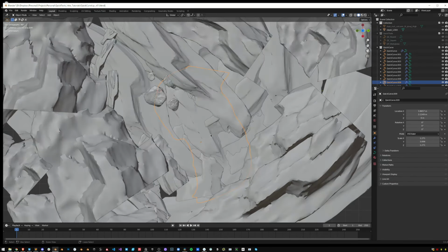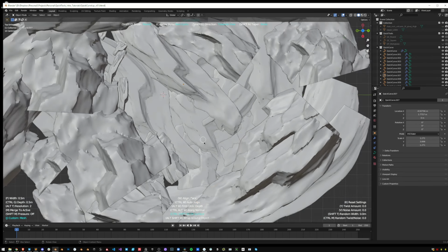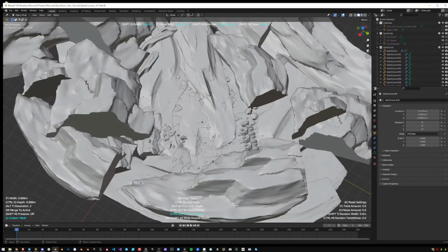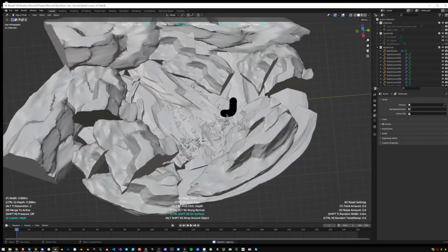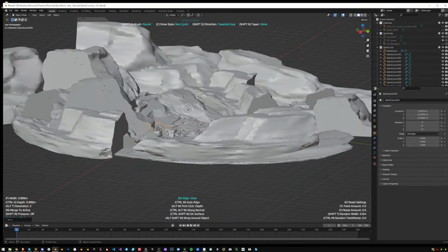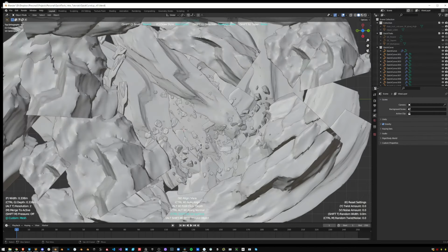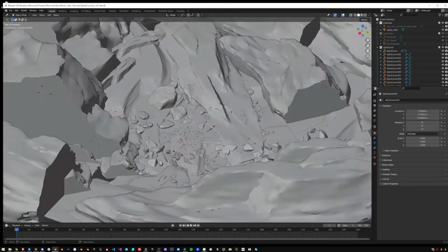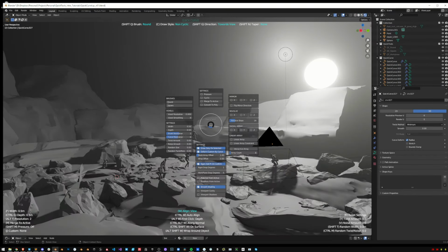You just want to make sure that you get this setting right. It's very important, this draw on surface, only on selected surface. So with that off, it doesn't matter what I've selected. It will just draw on whatever object it finds under my cursor. So here I'm just drawing a bunch of rocks. It's kind of like just a very artistic way to scatter some objects. And again, you can get all the variation based on size and your scale.